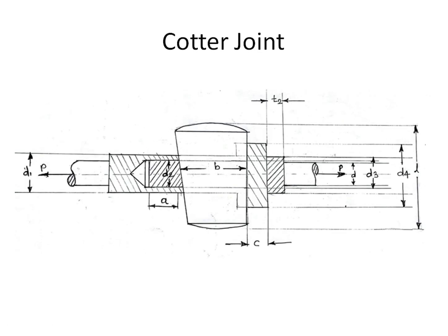The cotter joint is a type of joint which is used for joining rods which are subjected to either tensile load or compressive load, and these rods are joined together by means of a cotter which is used for fixing two components, namely socket and spigot. One rod is tied to the socket and the other rod is tied to the spigot. This figure indicates the sectional front view of the cotter joint assembly. It is necessary to understand the assembly of the cotter joint.